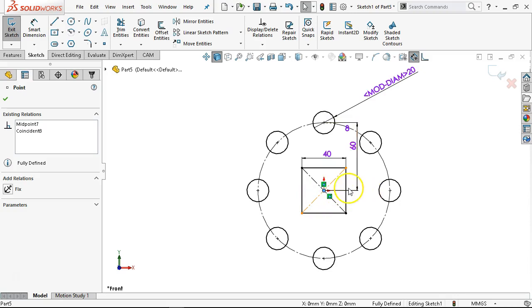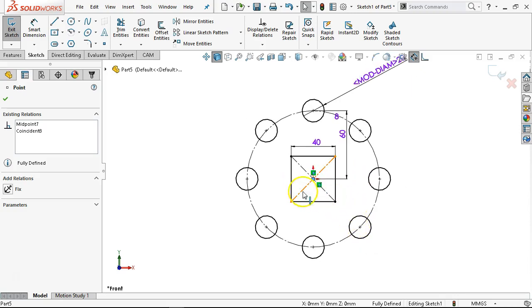All right, so I can't emphasize enough that when you get into the drawing and you do an instance count and your geometry was generated by a hole wizard feature, and this number is not 8, it's 9, it's going to be because of that automatic point.